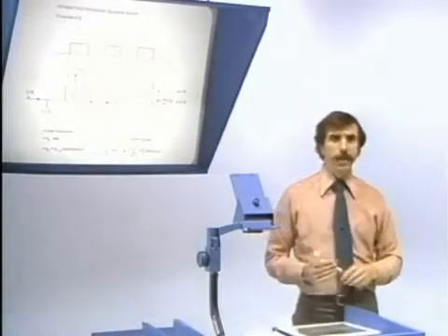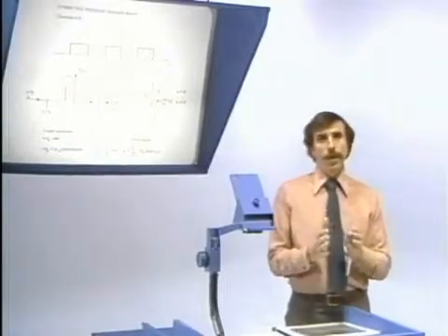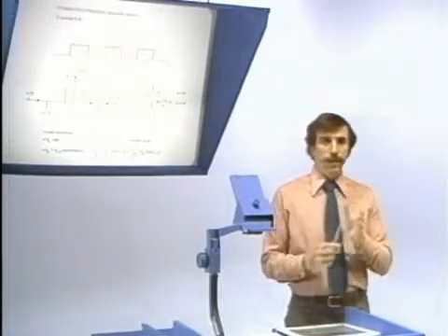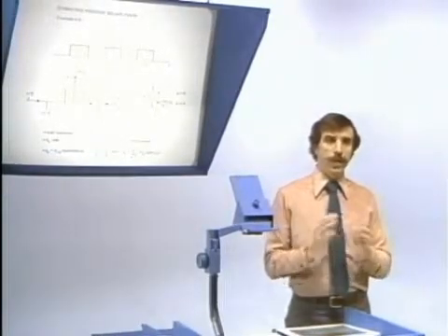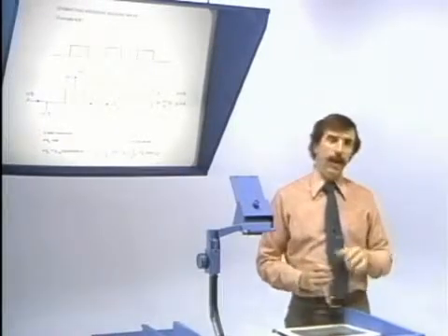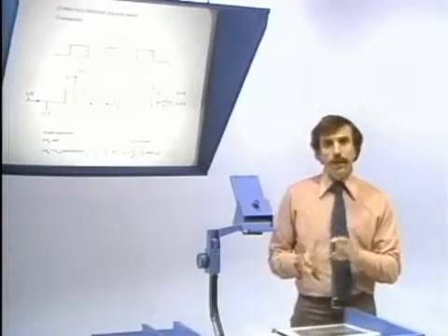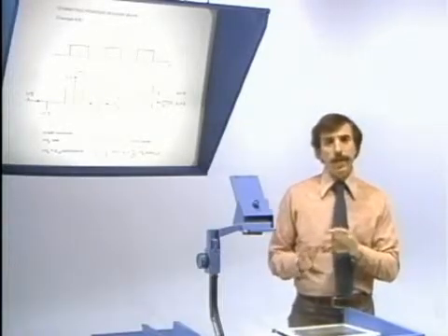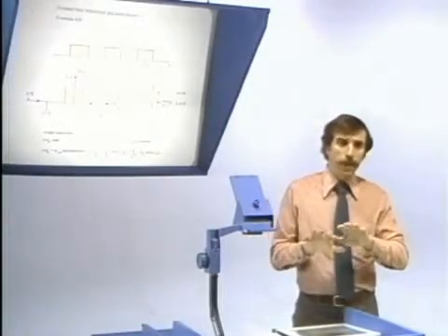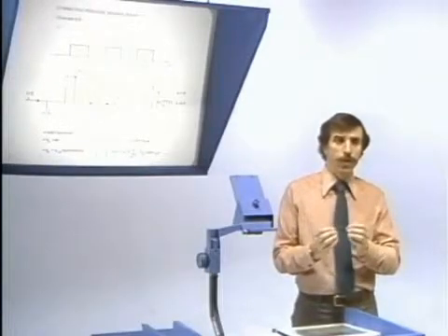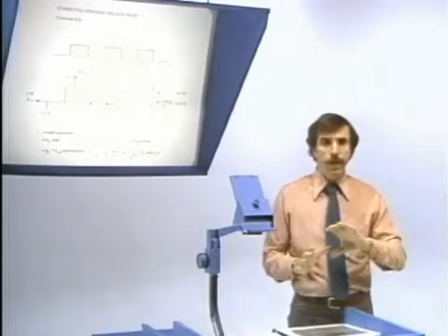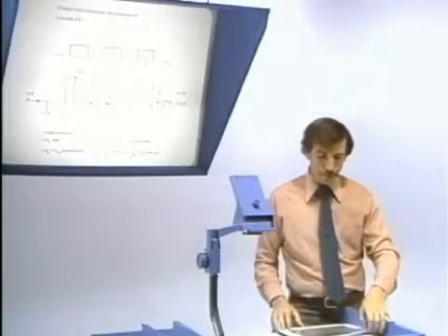And it really seems kind of amazing because the square wave, after all, is a very discontinuous function. Sinusoids are very continuous, and it seems puzzling that, in fact, you can do that. Well, let's look in a little bit of detail how the sinusoidal terms add up to build a square wave.